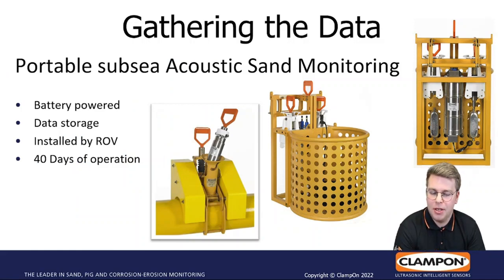So if you don't have room in the subsea control module, and or if you don't have power available, this is a field case where we have a portable subsea acoustic sand monitoring system. This is battery powered, and then it has data storage. It can be installed with ROV, and in this case it was 40 days of operation. So we have several solutions if you don't have the common system in place.